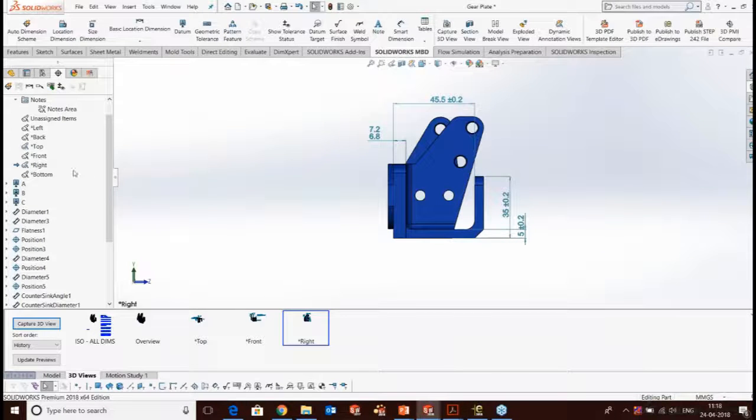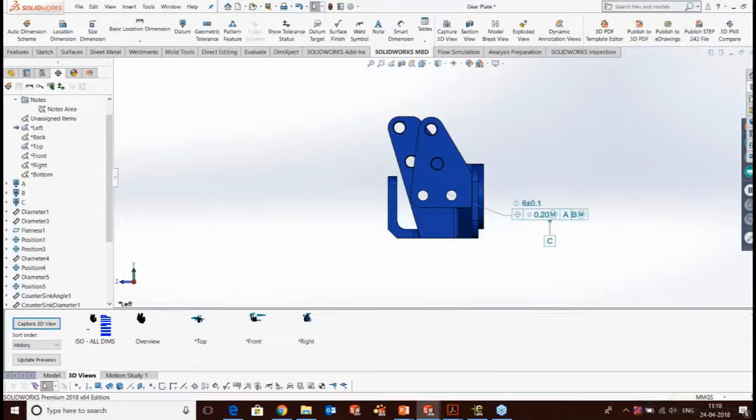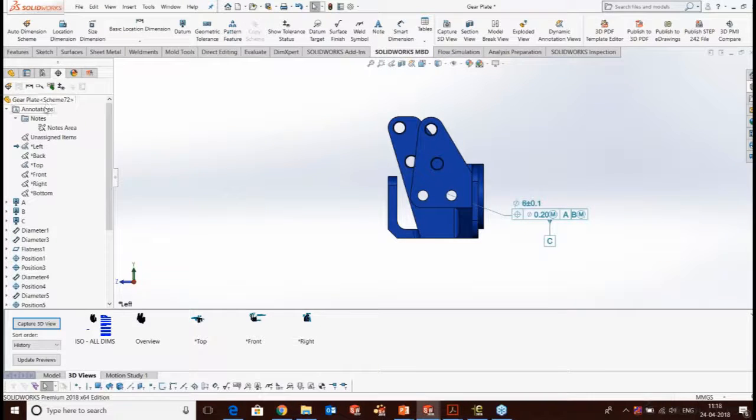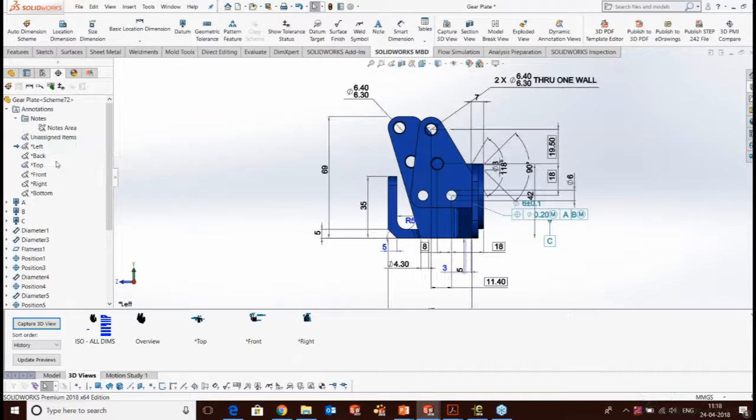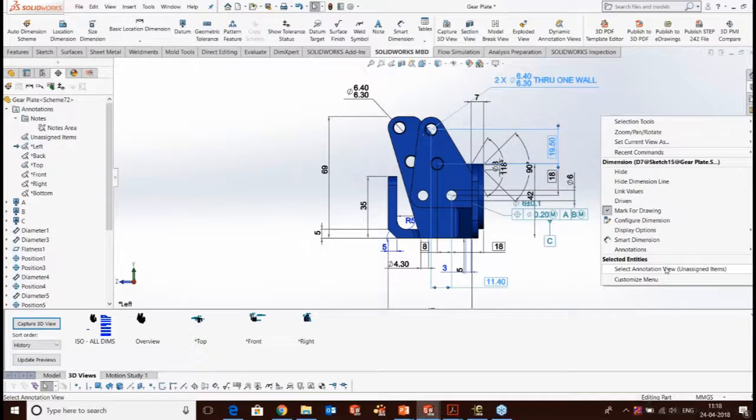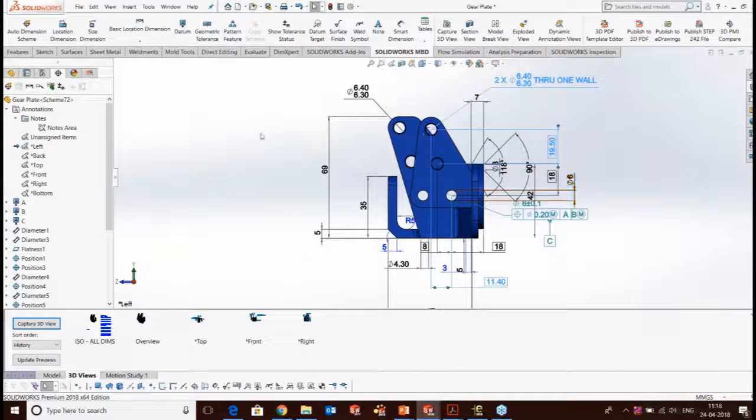So moving on, we'll just create one more view, that is the left view. So normally while creating a part, the user would have given a few pieces of information such as basic dimensions or the feature dimensions. We can directly leverage that information which we have given during our model creation. As you can see, these are the information that I had given while creating this part. So I can just directly use this in my document creation. I can just select what are the dimensions required, and I can just flip it out as we did earlier.